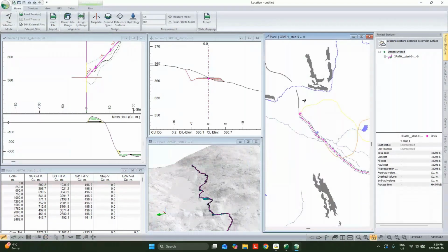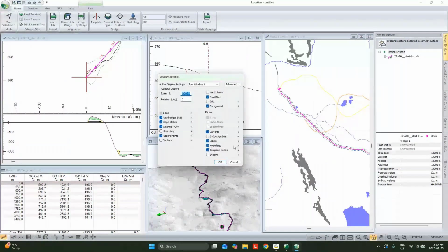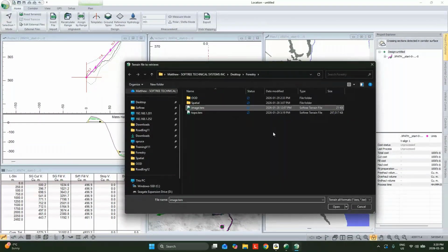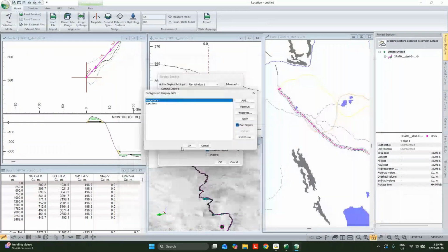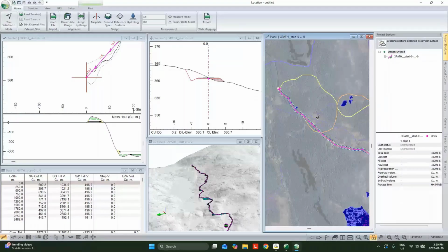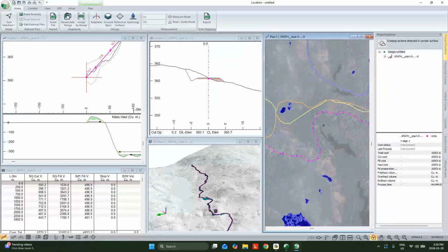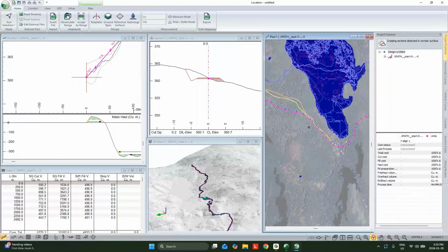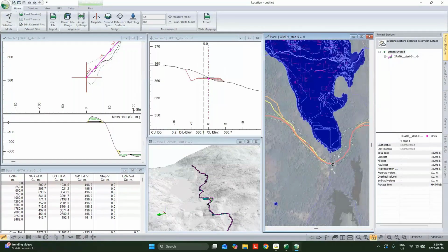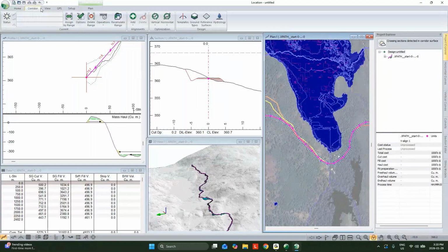So we took the time to add in that background image previously. Let's throw that in here as well. And well, we have that Path Explorer solution. Now it's considering our curve constraints, but is a polyline. So I'm going to take this and I'm going to run that polyline to alignment tool on it.